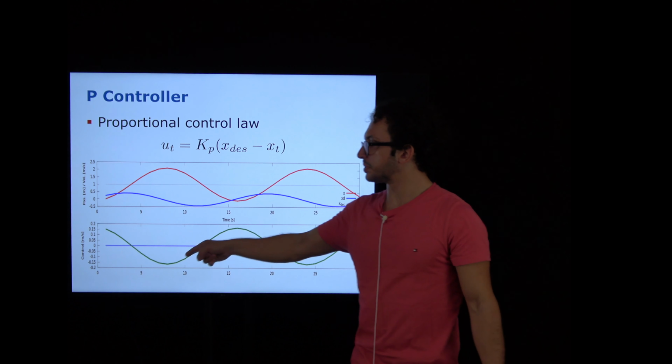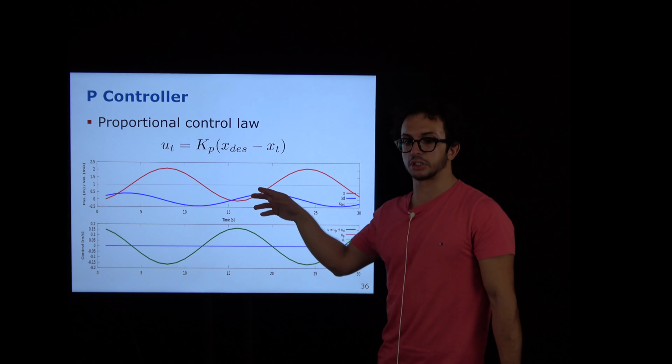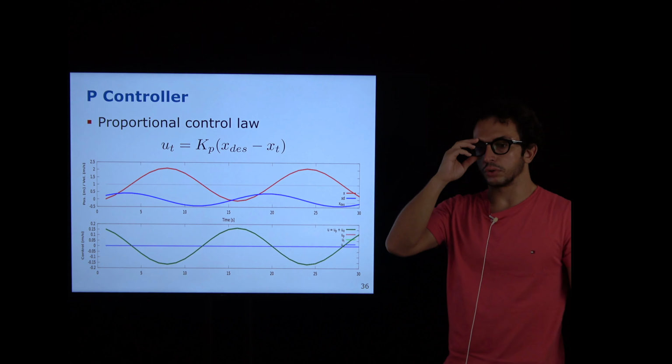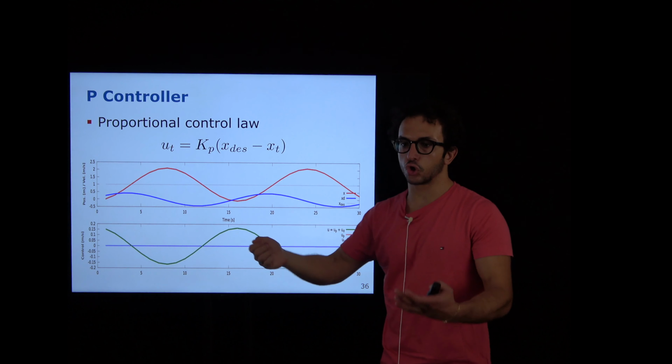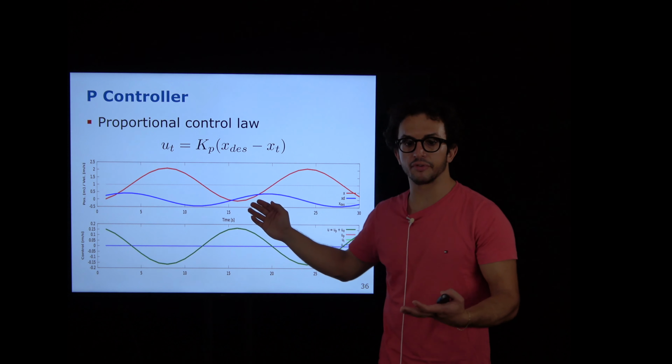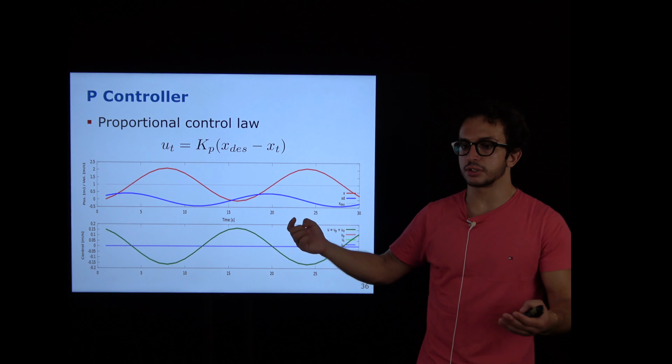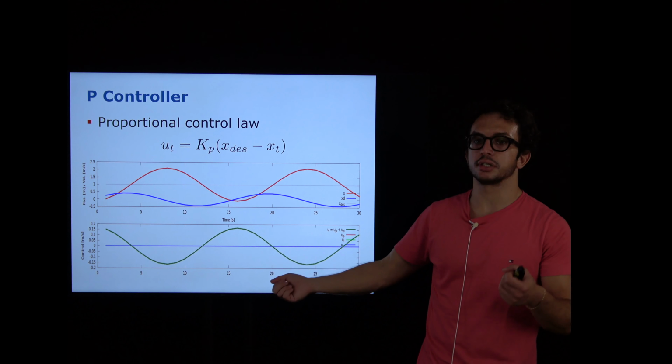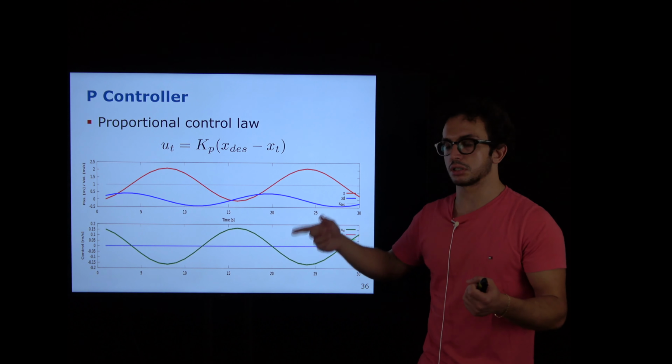And so this keeps oscillating in opposite direction and never stops. So the problem is that basically the controller detects the new error that it has every time and tries to steer the system in the opposite direction, and this causes the oscillations.